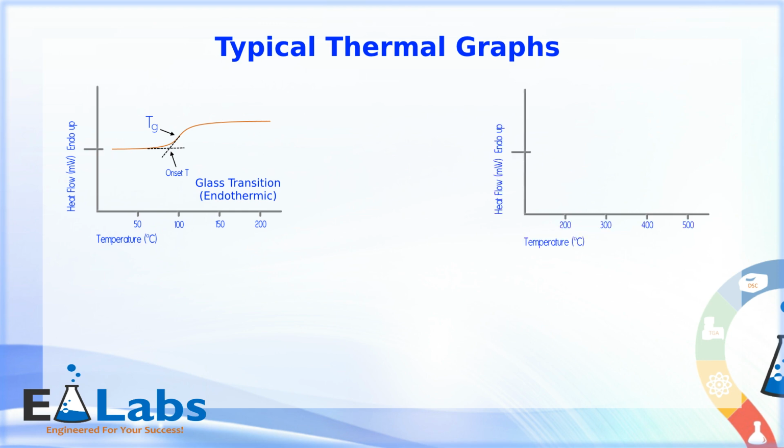Let's watch another thermal transition and tell me what you think it is. This melt looks visually different from the one shown a few moments ago, right? Melt transitions have their own shape, based on the overall shape, size, and physical characteristics of the sample, but generally they're large and somewhat sharp. Note the temperature scale for this graph. The temperature range is higher than the glass transition range in the graph on the left. Generally, a polymer melt will occur between 200 and 500 Celsius, though this is not a rule, just a generality